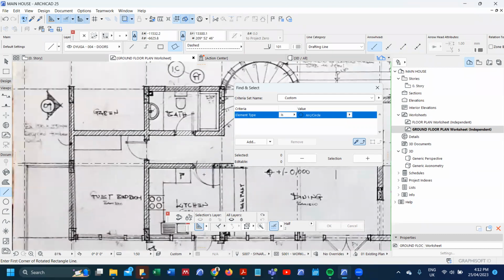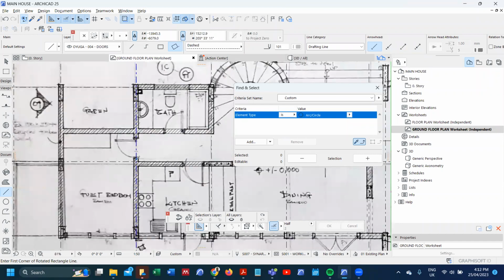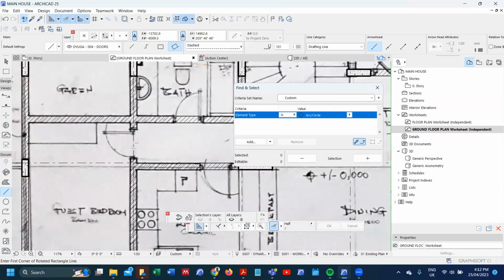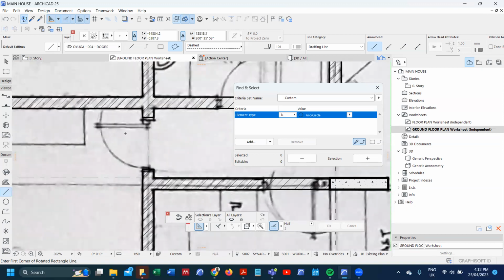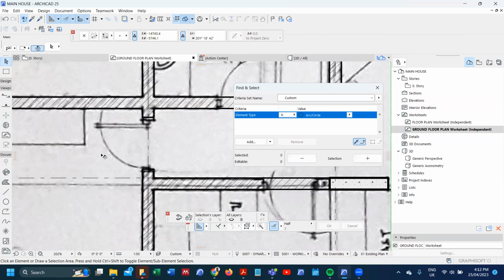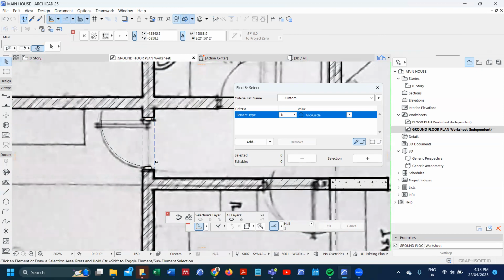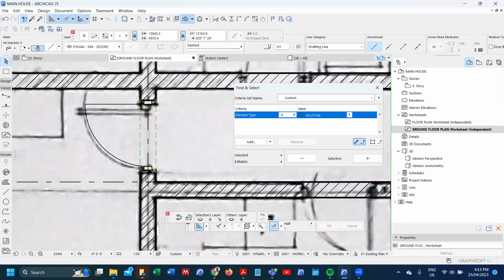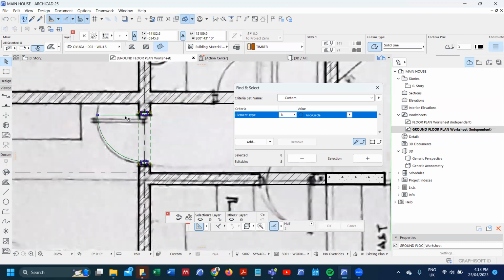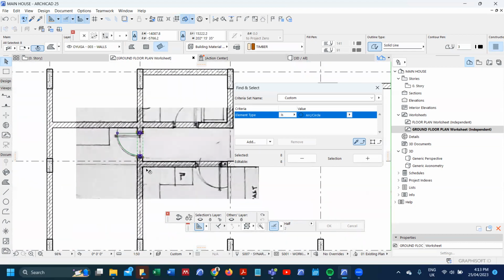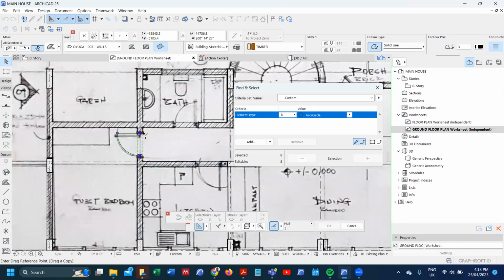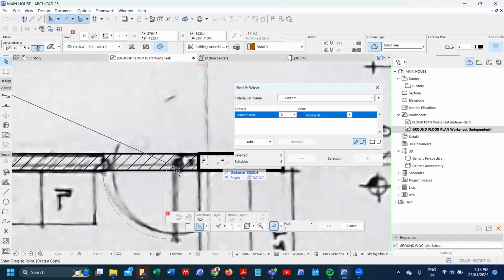Okay. And in our case, all what you need to do is just drag a copy of the same where they are needed. Trying to look for my hidden line simply because of the display order. I cannot get it. There they are. So I will group those three items, the frame, the swing, and the leaf, and the edge of the door. And that's what I'll be using for all my subsequent drafting of doors.